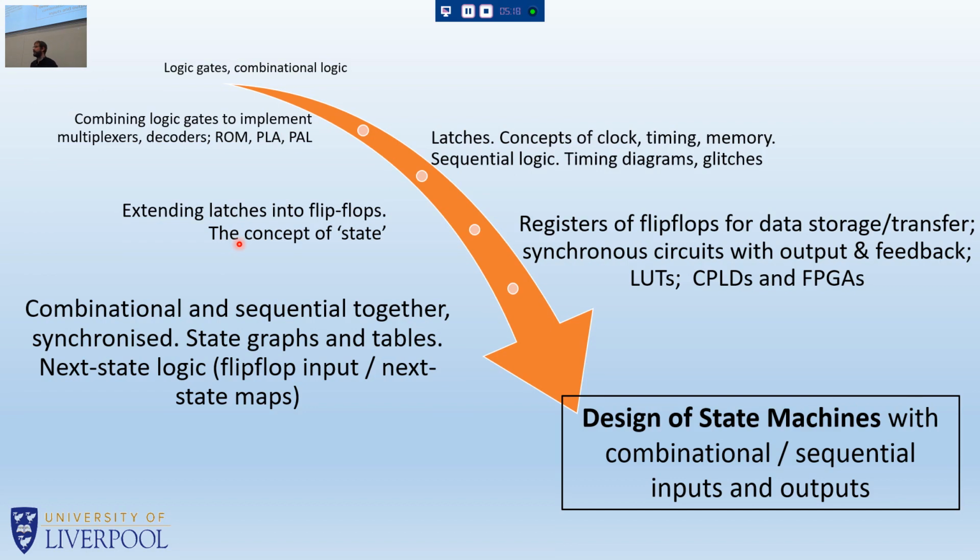Well, the difference is that a latch is not able to prevent all glitches, whereas a flip-flop is synchronized by the clock. So it's not just sequential, it's not just a device that accounts for a sequential signal taking time. It's actually synchronized. So, like synchronized swimmers, everyone does everything at the same time, right? So synchronized by the clock, everything's controlled and monitored by that tick of the clock. Now that clock is actually happening very quickly, maybe 50 megahertz or 20 megahertz, but we slow it right down in our minds and our diagrams because we know that each tiny nanosecond matters.